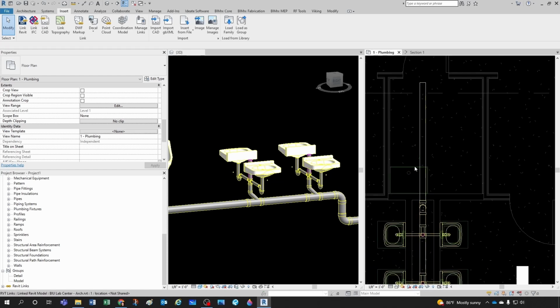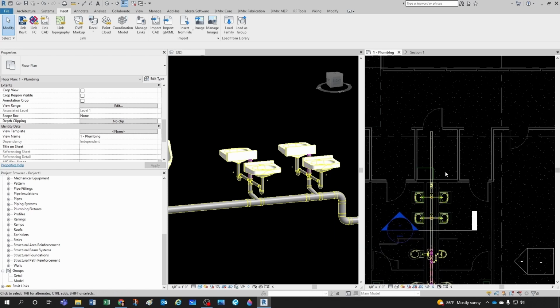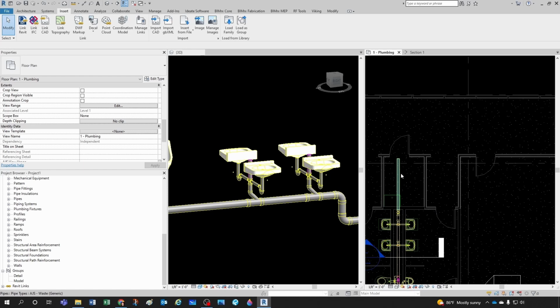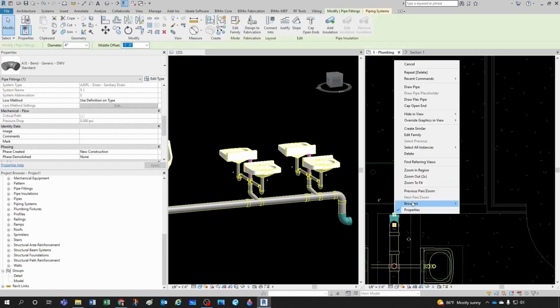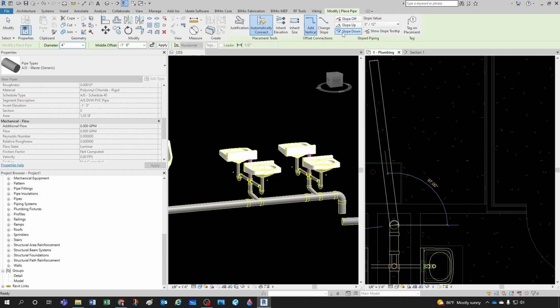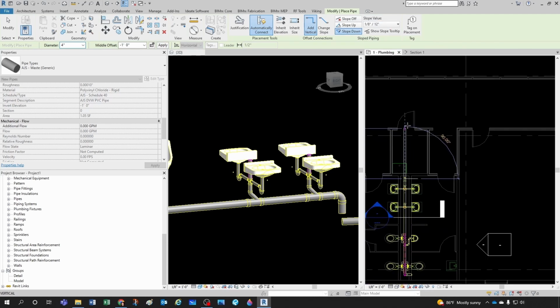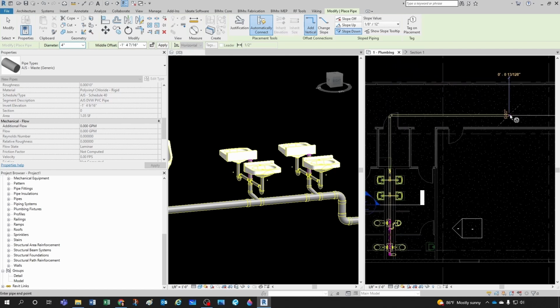And now we have a mop sink here. But before that, now we're getting into dangerous territory. This pipe should definitely be sloped. So let's go ahead and do things right. Draw a pipe. You want to slope it down. Since this is a large pipe, we can slope at 1/8 of an inch per foot. And let's say we're going this way, and then we're turning right.